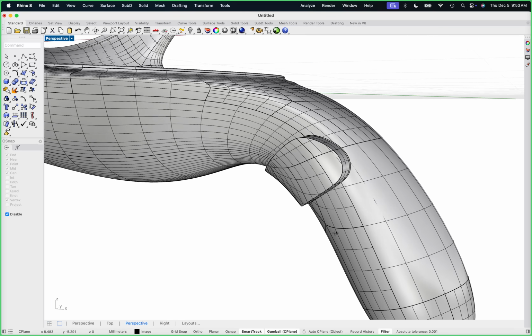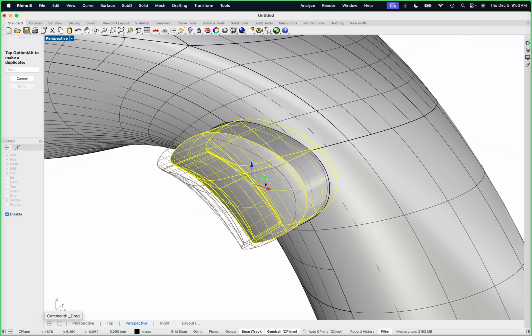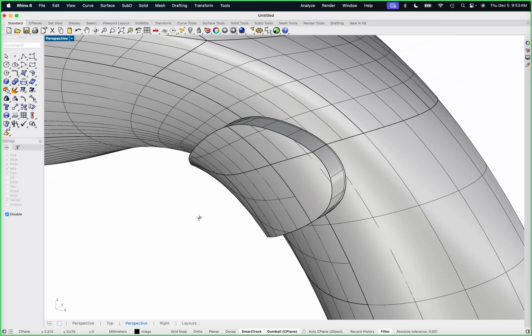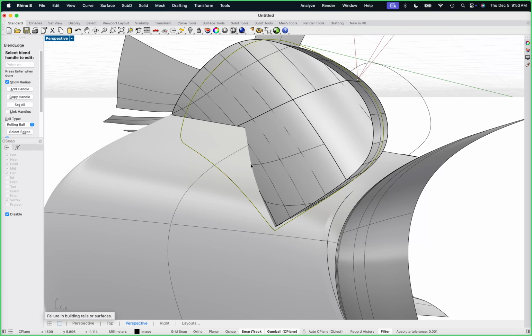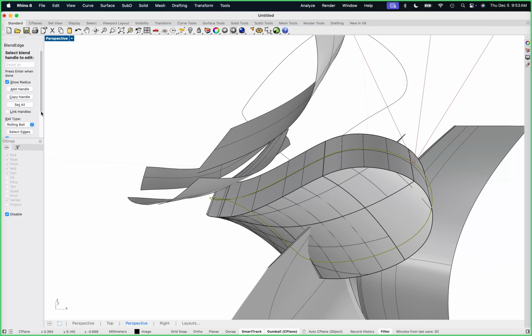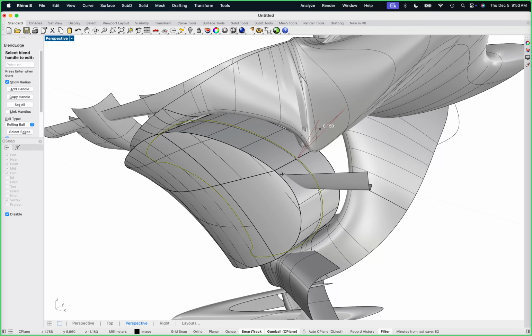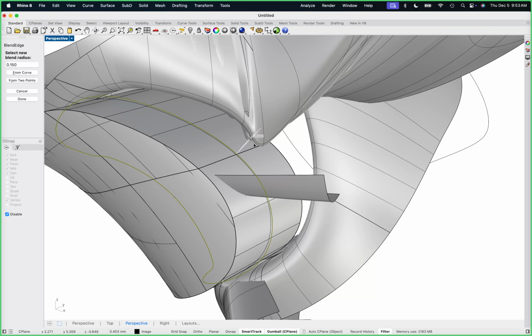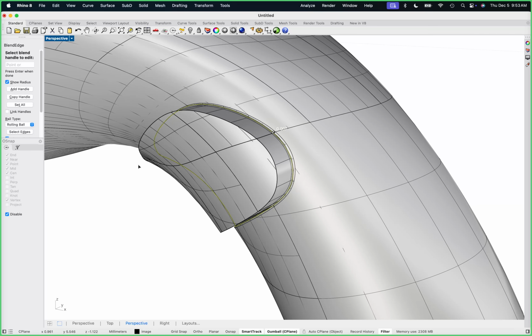And when I bring this back, I've got this thing that I can then just tuck inside here, kind of buttony like. I can apply a fillet or a blend or whatever I want to do to the edge of this thing, because this is just a nice clean NURBS object now. And my preview is way too big, so I'm going to set all, and I'm going to do like 0.15. And that's still too big, so let's drag the size in like that. And that's a little better. That gives us a nice little reveal on the edge of that, so we'll say OK.